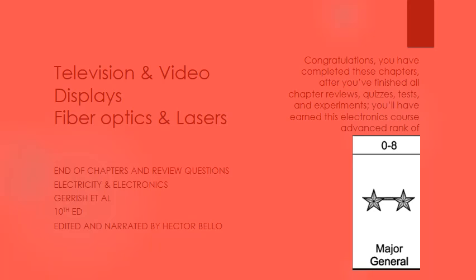The second generation provided a major breakthrough with the development of the microchannel plate, MCP. The MCP is a glass disc, 18 millimeters in diameter. Fiber optics are used to create millions of microscopic holes or channels through the disc. As electrons travel through these holes, they strike the sides, setting thousands of additional electrons in motion through the channel. The MCP multiplies the number of electrons thousands of times, producing a clearer image without the distortion characteristics of the original technology.